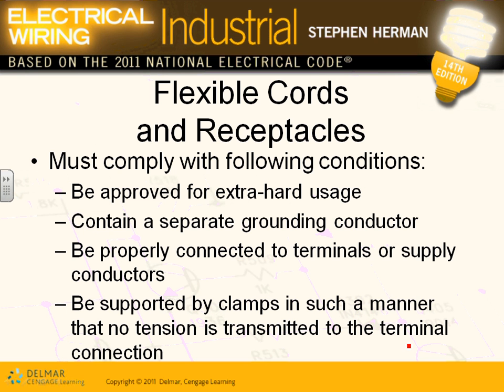Flexible cords and receptacles. Can I use cords and receptacles in a classified location? Yep, no problem. If you're using them, the cord has to be extra hard usage in these locations. If it's in a Class 1 Division 1, it has to be explosion proof. Other than Class 1 Division 1, they can be only extra hard usage.